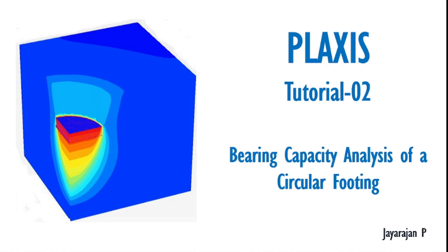This is tutorial number 2 and provides the bearing capacity analysis of a circular footing. This tutorial is very similar to tutorial 1 except that in this case the foundation is taken to some depth, that is the actual depth of excavation, and the foundation will be modeled as a plate element facility available in PLAXIS. So let us go straight to the problem statement.